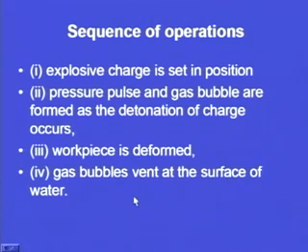So, the gas bubbles then vent out at the surface of the water. This is the very basic principle of explosive forming. The punch is not used. Whatever deformation of the sheet metal is taking place, it is taking place under the impingement of the pressure pulse that has been created in the water using the explosive.